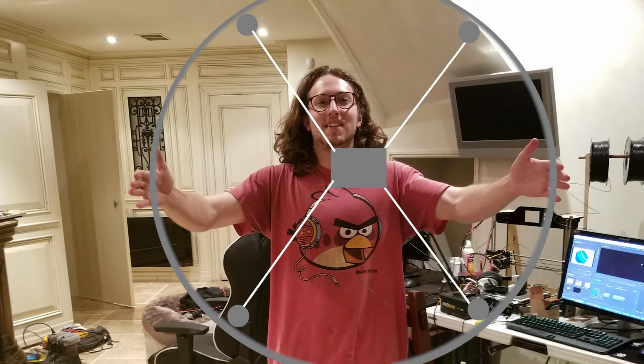The reason we chose this way of aiming the device is because it's far more energy efficient and stable than using propellers alone. An electrolysis apparatus and condenser apparatus will also be in the balloon. These are used to replenish hydrogen lost to diffusion through the balloon material. This regeneration of hydrogen allows the balloon to fly indefinitely. Additionally, on the inside of the device would be air compressor tanks used to change the mass of the device and control altitude.